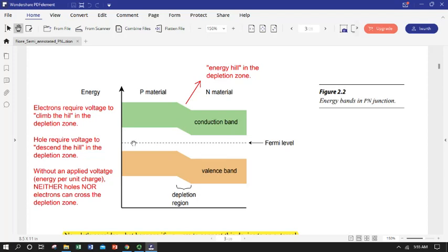And over here in the P-type material, it's closer to the valence band. It's not in the middle. It's closer to the valence band because you've got those acceptor levels where holes can jump down, because holes have to jump to go down into the valence band where they can conduct like crazy. So that's what we went through last time.